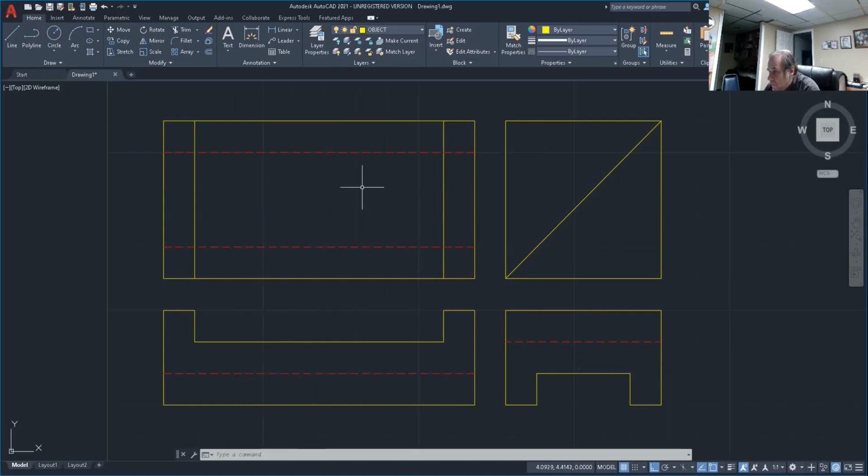Now, if there's true size and shape in the top view, that means I have to dimension them in the top view also. Okay, so if you look at your drawing, we know that that first hole right there, let's see if I can read this here, is over 1.25. So I'm going to offset this line here over 1.25. Then I'm going to come over another 1.5 inches, and that's going to give me the distance this way to locate my hole first of all.